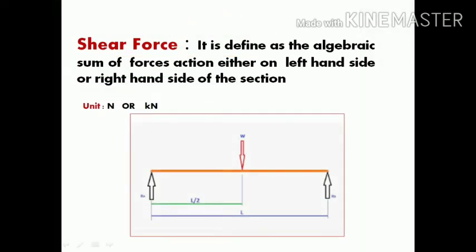Now, the definition of shear force. What is shear force? The shear force is the algebraic sum of the forces acting on either the left hand side or the right hand side of the section of the beam. Here it is a simply supported beam and W load is acting over it in the middle of the span, and the length of the span is L. If I take one section from here,